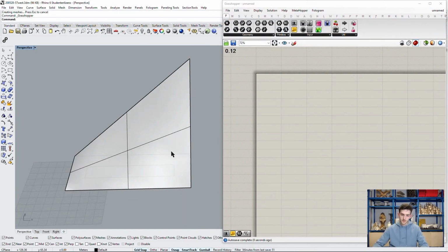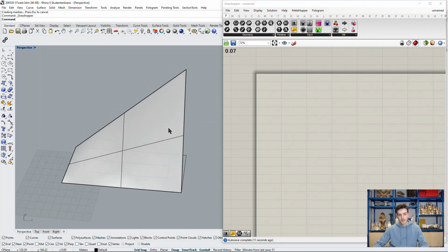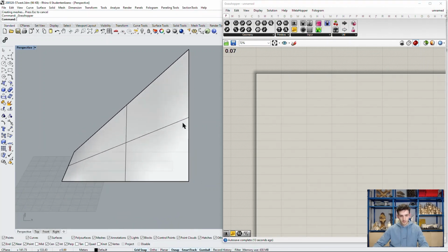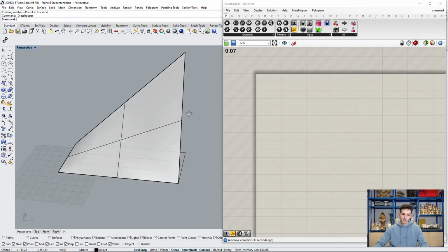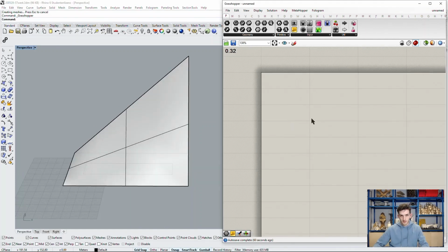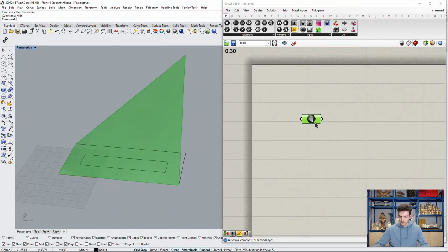The building itself, of course, has this courtyard cut into the roof structure, but as its panelization is continuous, we will first work with this whole surface and then cut in the hole at the end. So what we'll do today is examine how exactly we can panelize the surface in different ways, and with this get step by step closer to the actual surface of the 57 West. Of course, we need to reference our geometry in Grasshopper. We can now hide this and work with this geometry only.